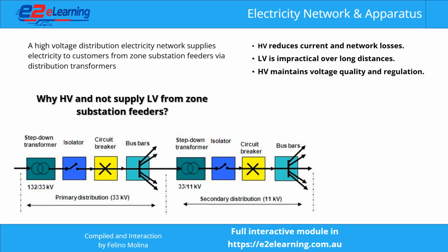Low-voltage feeders experience large voltage drops as load changes throughout the day. High-voltage feeders maintain stable voltage, with local transformers providing consistent LV supply. Long LV feeders produce very high fault currents at the substation and along the feeder. These high fault levels increase arc flash risk and place unacceptable stress on switchgear.